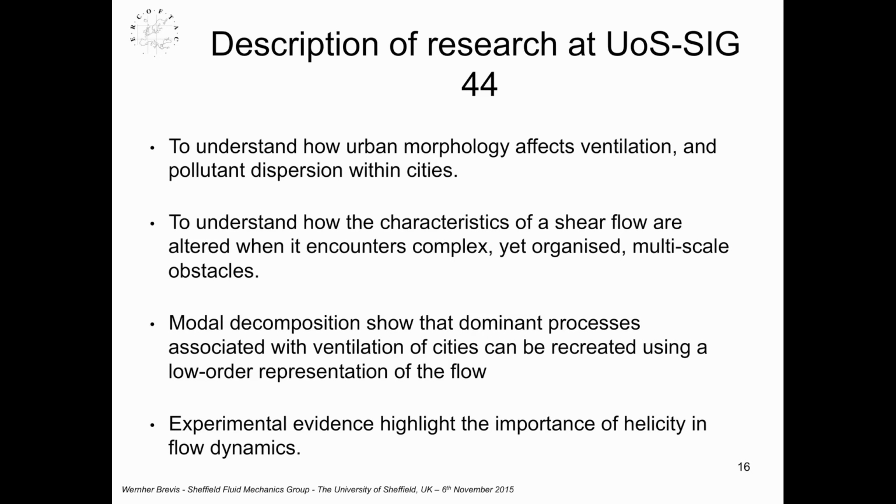So our objective is the quantification of the large-scale turbulent structure produced behind these wakes, and to do that, we are basically using as a benchmark a regular obstacle. Now, for this, we were using a three-dimensional velocimetry system that is being sketched at the bottom right part of the slide. And with these results, we have been investigating the role of some fractal properties that you might not be familiar with, but they are quite easy to obtain, which are the fractal dimension, linearity, circularity, and other parameters that we use to represent these complex geometries.